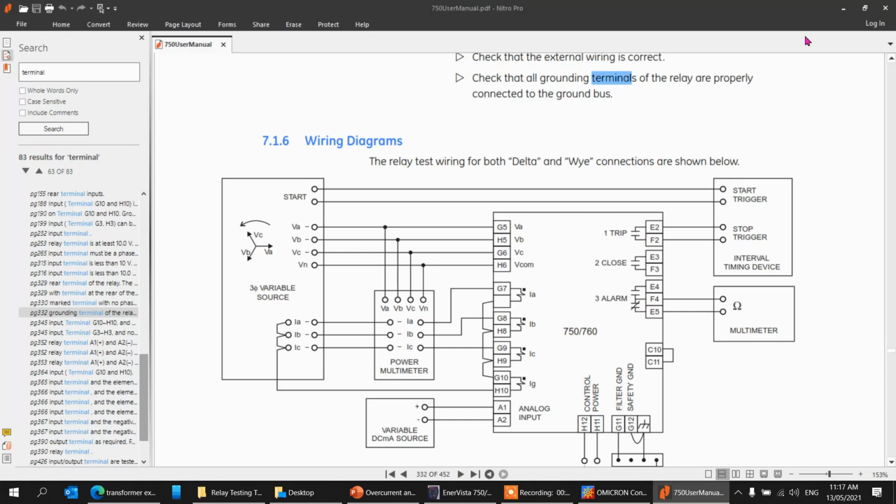It's easy. Let's say you have a multimeter. I put the multimeter here to Earth, and if you don't have any voltage there, it means the control system is not earthed. But if you put your multimeter in here to Earth and you get half of the voltage, it means it's earthed. If there is no half of the voltage, you need to find neutral. But don't focus on that first. We do the basic one. It's a little bit advanced, but it's a good question.